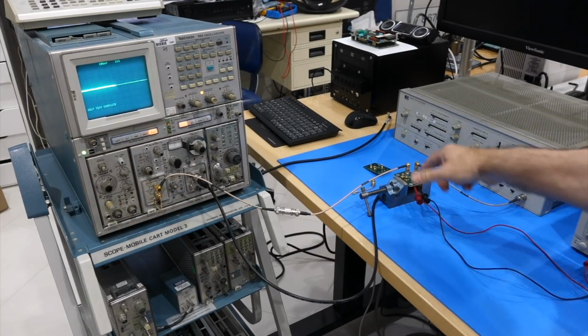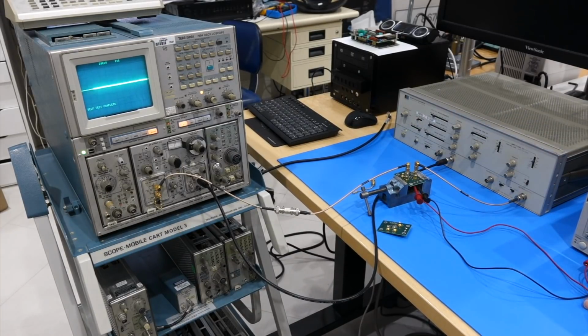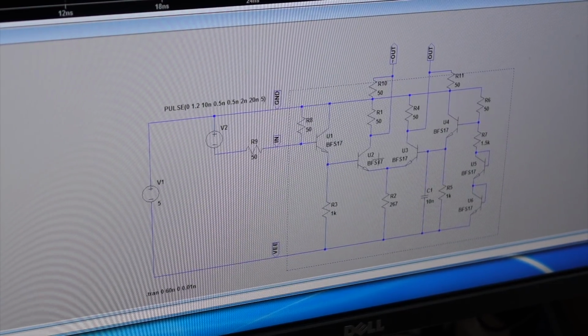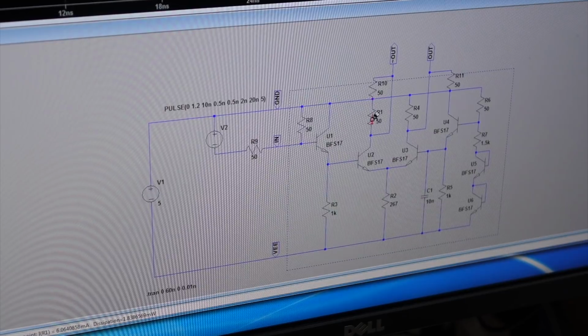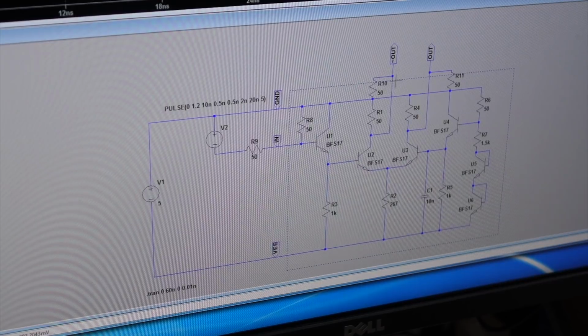And I put my second board, the other one, and it's exactly similar. So the pulse inverted, it's plenty fast, but it has the wrong amplitude here. So I might have gotten my resistor wrong, the one I tweaked. Maybe I shouldn't have tweaked them. So I think this is perfectly normal. I'm a doofus. What's happening is just that I'm measuring it not on 50 ohms, but on 50 ohms in parallel to 50 ohms, which is on my instruments, around 25 ohms.